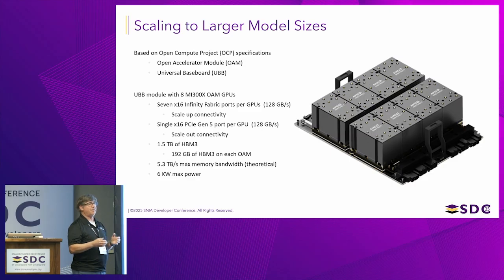You have to pack these things close together because you have an SI problem. You can only drive that interface so fast before the SI channel, the signal integrity, degrades to the point where you can't spread them out anymore. So that's one of the reasons these things are packed so close together, to get all of that information over a very, very high bandwidth interconnect. You have to have them close together. So that limits the number of GPUs we could pack together, and also the number of pins each interface consumes to pack it all together.